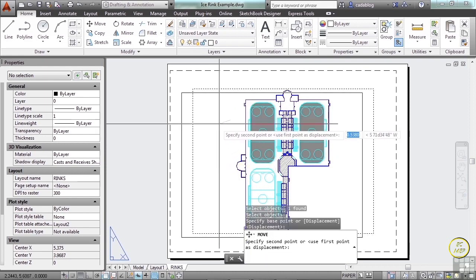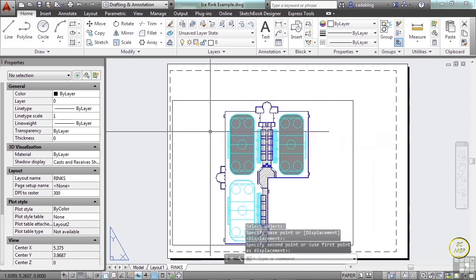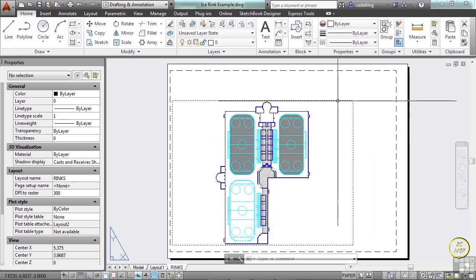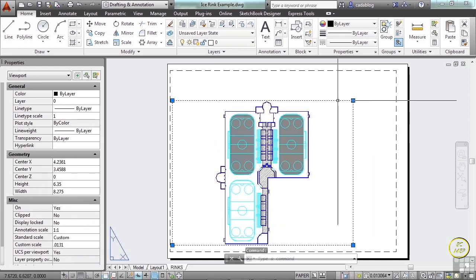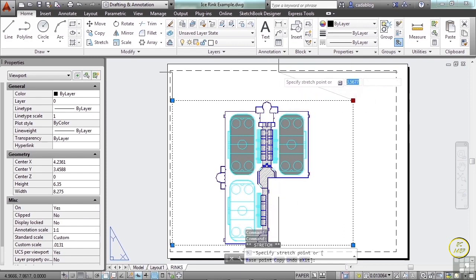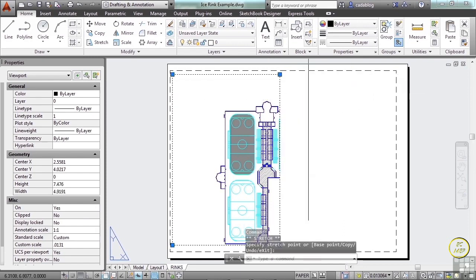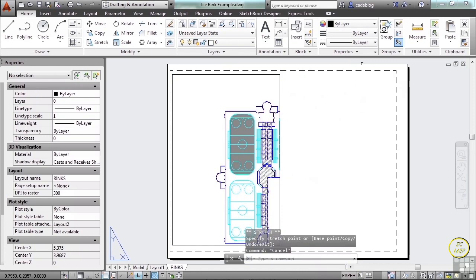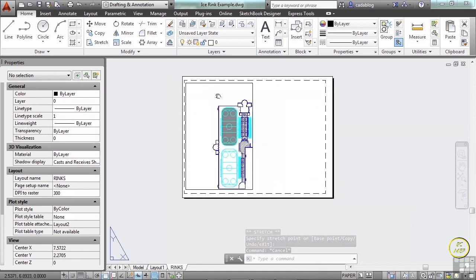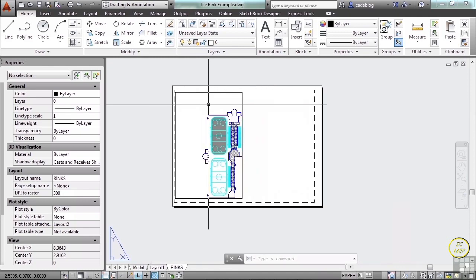We're going to move it to the left, and then we're going to resize it so that it only fills up about half of the drawing. So just select it like you would any other object and grip edit. Just stretch it over. Now in this viewport, you'll see this hard line. That's the edge of the paper. Whatever size this drawing is set up to right now, and we'll talk more about that later on in the next few sections when we talk about printing.